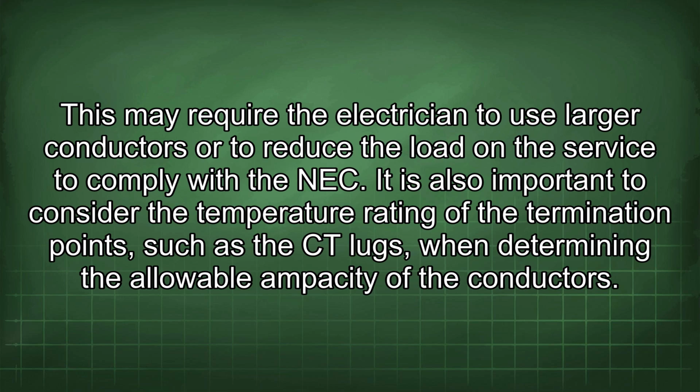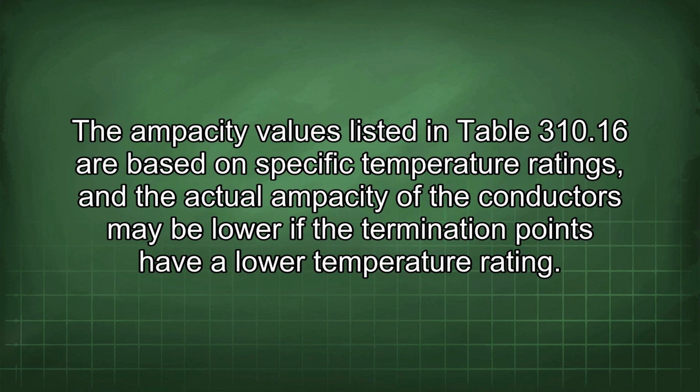It is also important to consider the temperature rating of the termination points, such as the CT lugs, when determining the allowable ampacity of the conductors. The ampacity values listed in Table 310.16 are based on specific temperature ratings, and the actual ampacity of the conductors may be lower if the termination points have a lower temperature rating.